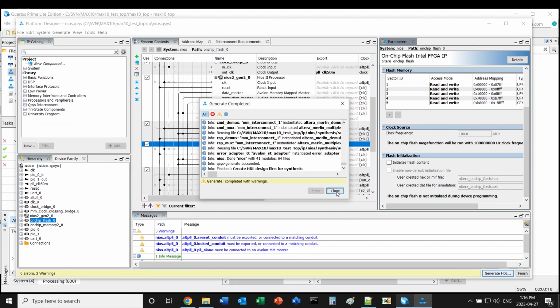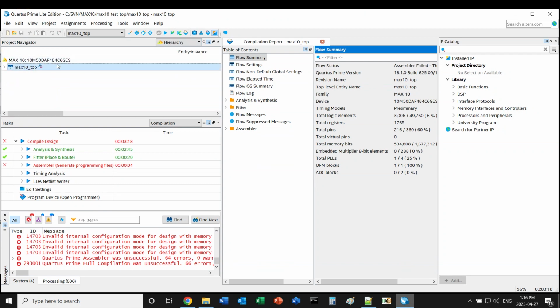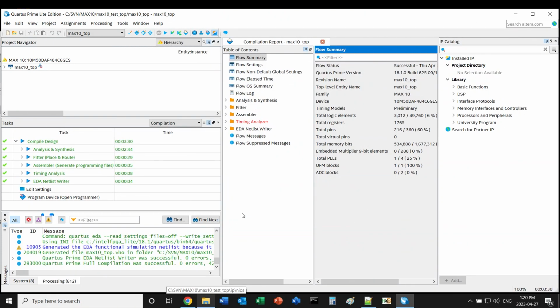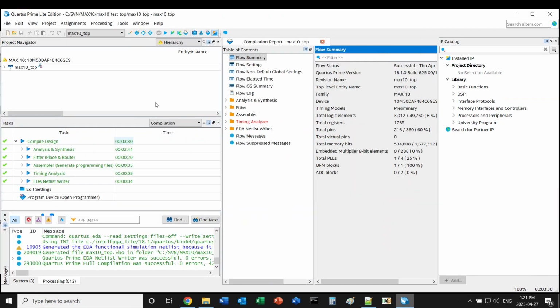Okay, the IP code updated, and then we just recompile again. Now the compilation is done, no problem. As you can see, Quartus generates the NIOS hardware information. We are going to use this as the BSP information to bring into NIOS Eclipse. Let's open Eclipse.